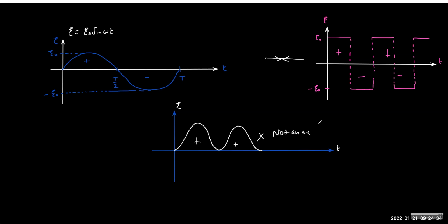So AC does not mean fluctuation. Fluctuation, meaning variation, is not called AC. AC means change of direction. So any mathematical equation which can have a positive and a negative value over a finite interval, we call AC. And when you complete a cycle, we call it one cycle or one oscillation. So for anything which is AC, we calculate things for a cycle by default.